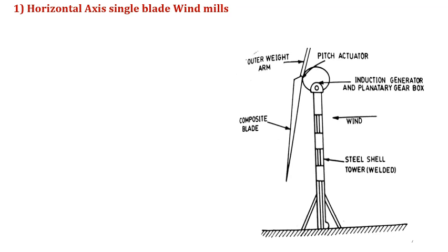If extremely long blades, say above 60 meters, are mounted on a rigid hub, large blade root bending moments may occur due to tower shadow, gravity, and sudden shifts in wind direction. To reduce the rotor cost, use of low cost counterweights is recommended to balance the long blade centrifugally.